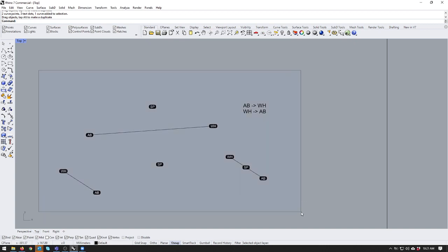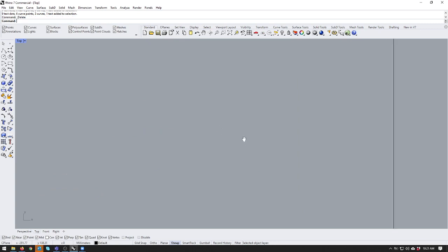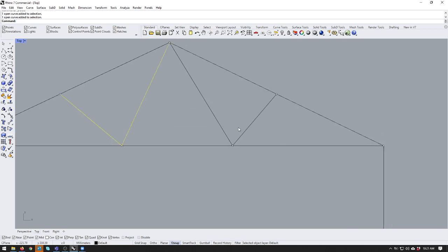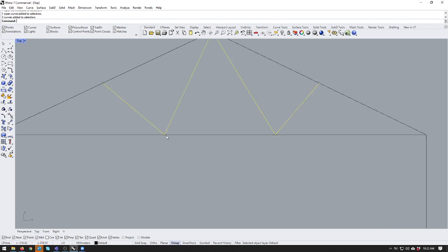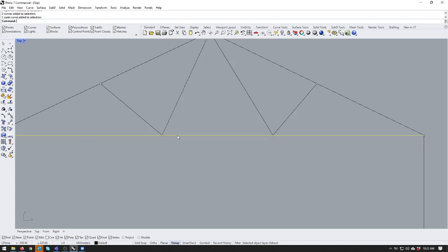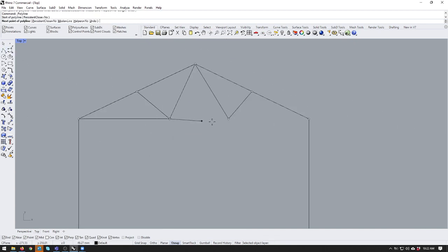Now if I transfer this into more of a structural diagram, see this line that I've drawn? The line goes from this point to this point. So it's almost like saying we're going to connect this node, this connection of members at this point, with this beam. The system won't know that we're intending the webs of this truss to be joined to this cross beam, the bottom flange. It doesn't understand what's happening there, so it needs to know that you want those connected by having separate lines going from each node to each node. Okay? Does that make sense?